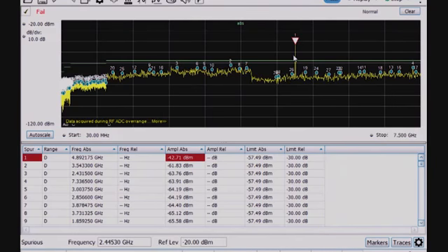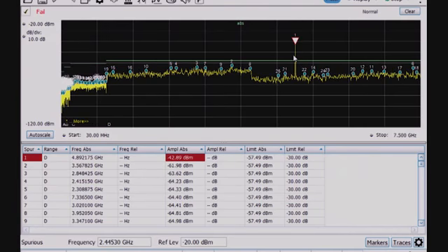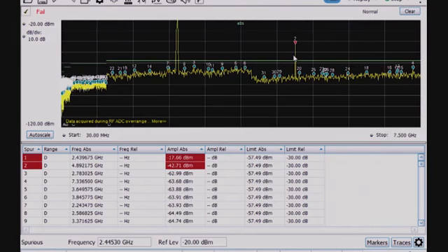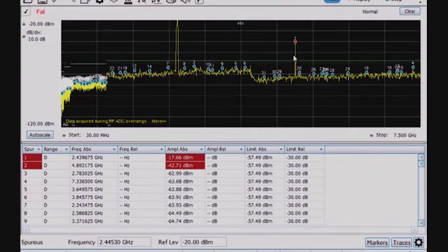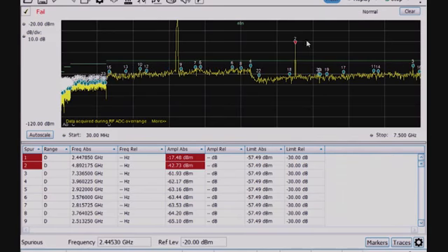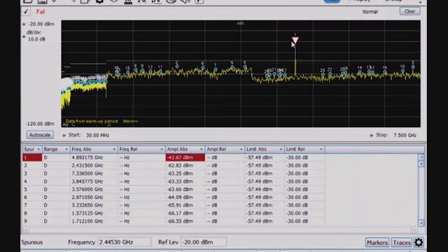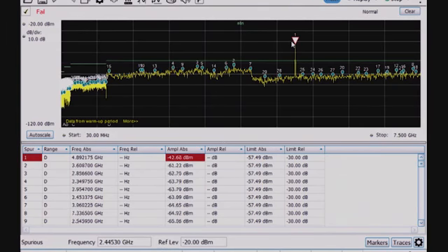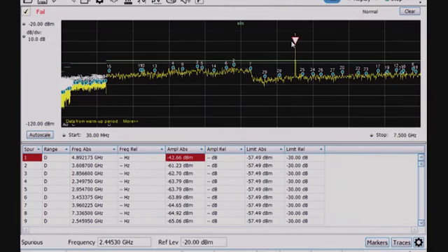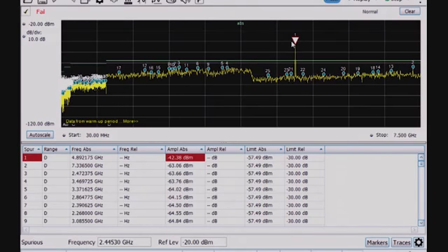So this is the type of EMI test that I would need to do for unintentional radiated signals. This is a good conservative estimate. It gives me pretty good confidence in this case that I would not pass final EMI compliance, particularly because of this second spur here that's always present. So I'll have to go back and look at that design to make sure I can fix anything that's wrong there. Maybe add some shielding, or look at the leads. Maybe there's some pickup from a power supply. Somehow I'm getting a second harmonic there that's causing me to fail this EMI pre-compliance line.